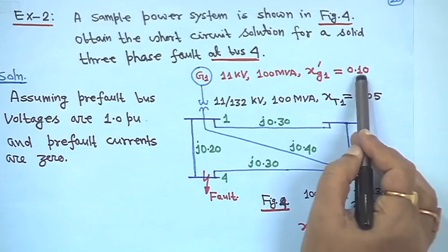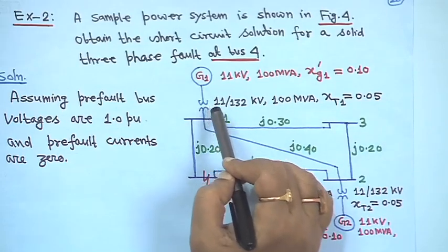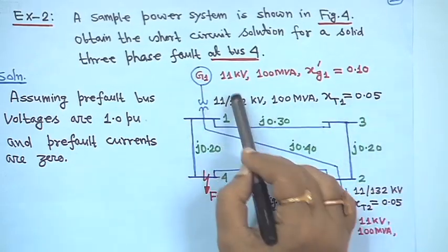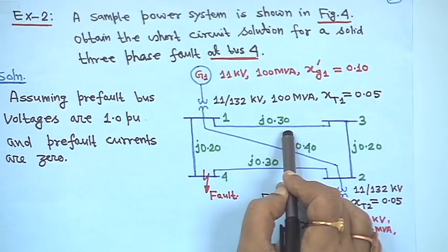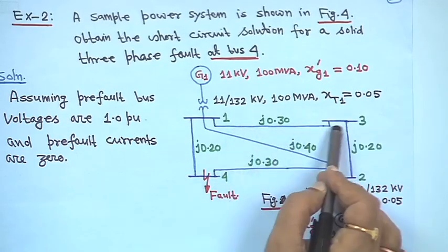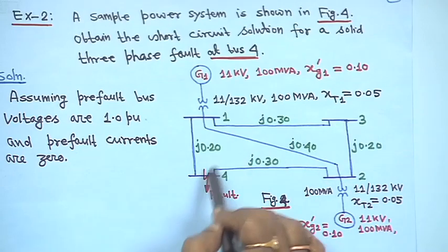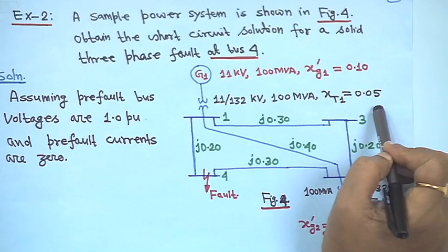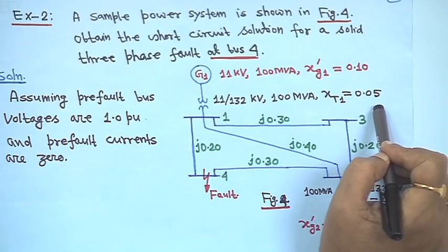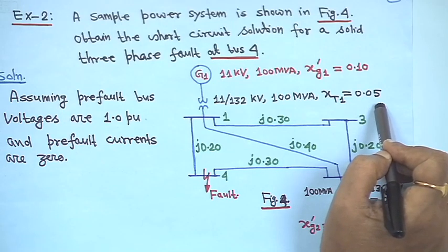That means the 0.05 and 0.11 here are in series, so 0.15; this impedance is given. So you have to find Y13, Y12, Y14 plus, say, Y10. That means with this 0.1 and 0.05, you construct the Y bus matrix.